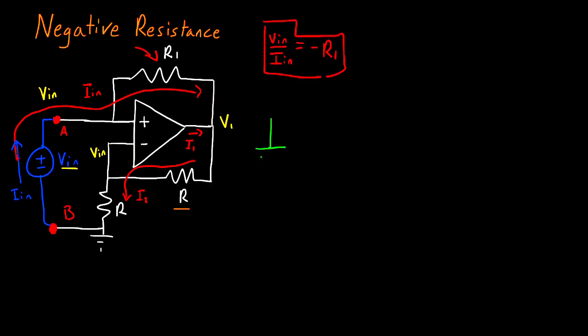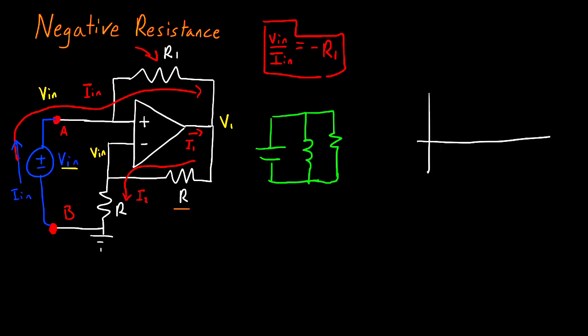Say I have a capacitor in parallel with an inductor, and these two are connected to a resistor in parallel. Now, if I have energy stored in this circuit, whether in the capacitor's voltage or the inductor's current, and my resistor is sufficiently large, this circuit will oscillate. The output voltage might look something like this, where you have this exponential decay behavior, and that decay is due to energy loss in my resistor and in parasitic resistances in my inductor and in my capacitor.